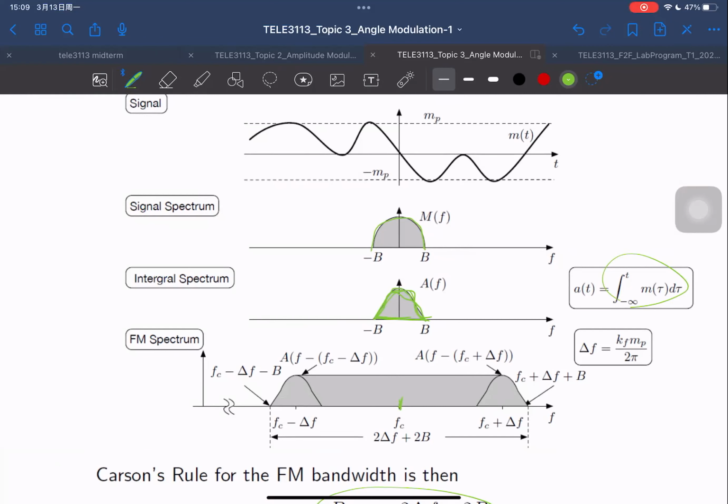Because when you multiply two cosine functions together, the first time you apply your trig identity you take a half, and then when you apply your Fourier transform, you take another half. So your amplitude is essentially divided by 4 now, so it's AC over 4. And if you look at the second term, you get another half, so 1/4 times 1/2 again equals 1/8. Does that make sense?